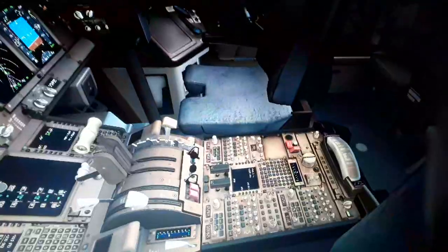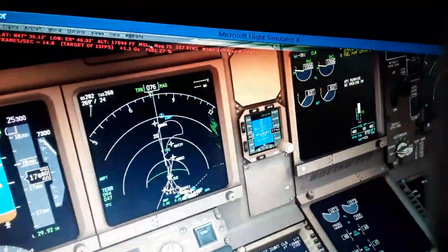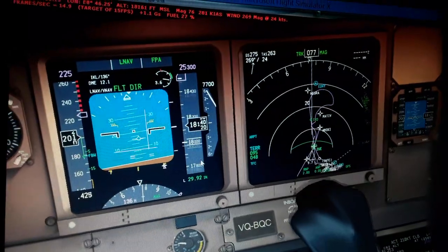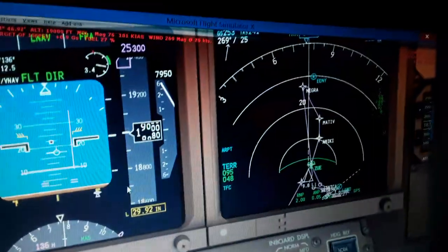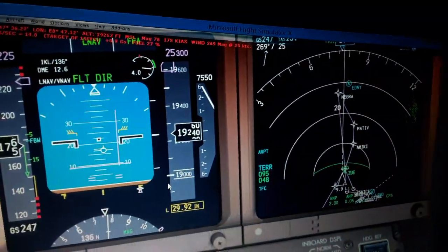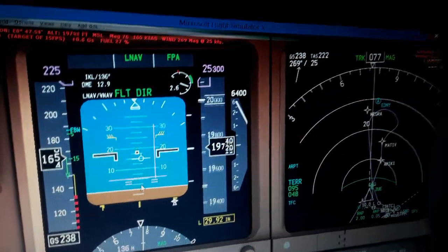You can see I'm stabilizing using the pitch frame, also the control columns here. It's the waypoints, you can see the climb bar. So we fly with this airspeed, Mach 0.4, about 500 kilometers an hour. Climb with 7,000 feet. So I need to reduce the rate of climb right now.